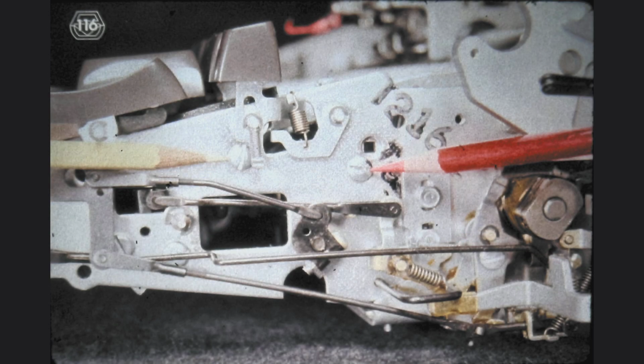These are the screws for the right bail support plate. On the inside of the keyboard frame, you can easily find the plate which holds the bails in position. When we want to adjust the parallelism of the bails, we must loosen only the screws on the right bail support plate or only the screws of the left bail support plate at any one time. Once a plate is loose, we make both parallelism adjustments.